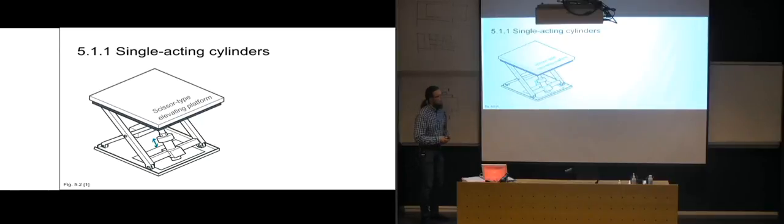But the point is, due to the scissor effect here, all of the weight pushing straight down is going to be pushing straight into the cylinder no matter what. So when it gets down to being almost flat and the cylinder is almost horizontal, then the force is still going straight into the cylinder due to the lever and momentums going through these scissor arms.